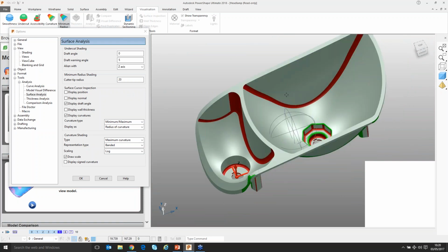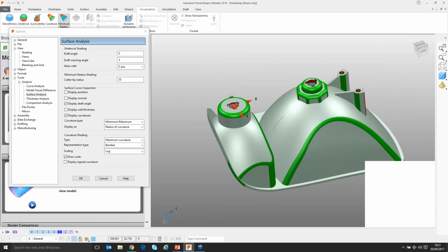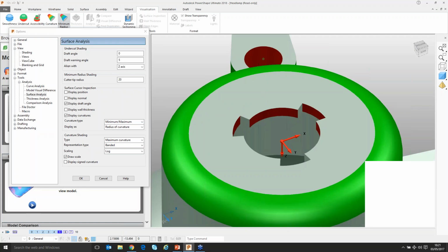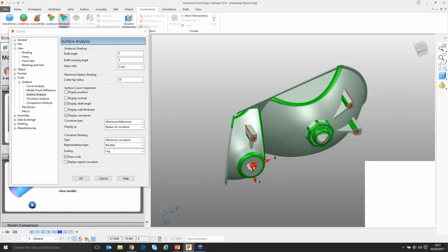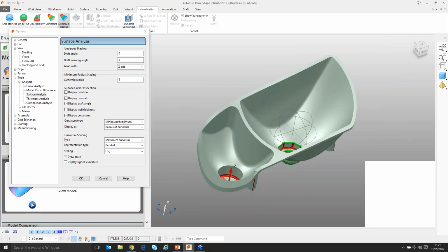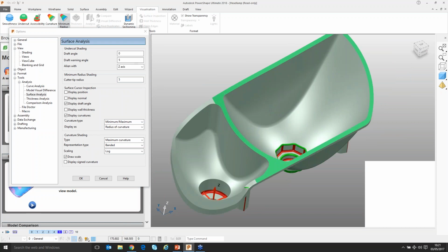On the opposite side of the tool, of course, it's going to be, again, the same. Convex, concave would be red, like so. Okay, so that's the minimum tip radius shading and how you actually access the value that you've got to interpret what the numbers mean.